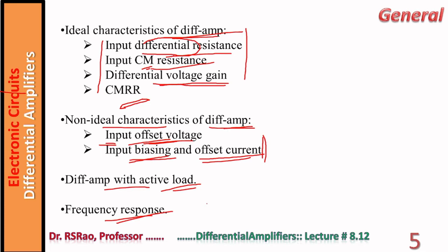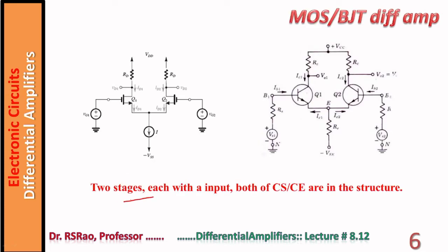Here are shown differential amplifiers. The first one is the FET version, the second one is the BJT version. Two stages one can see. As already mentioned, the speciality is that these two stages should be as identical as possible. It implies the RDs should be identical, their resistances, their power dissipation capabilities, everything.